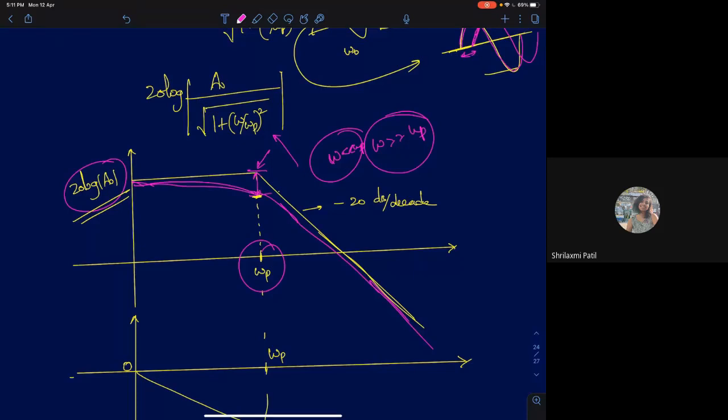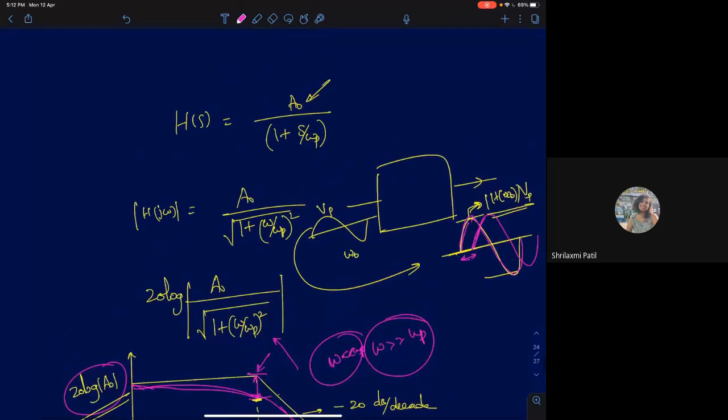So it can tell you how close to instability you are or how stable a system is. So that information you can gather from the phase response as well. Of course, it will be coupled with magnitude response, but phase response will give you that information. In open loop, it may not have a direct application, but when you have a system in feedback, in a closed loop system, phase response will have significance. So that's why we'll try to plot the phase response for this function.